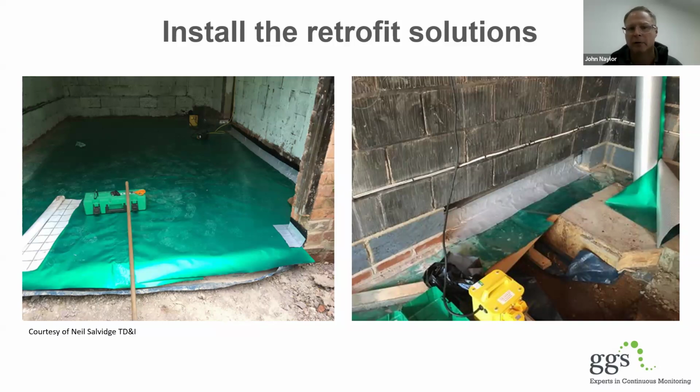So rather than knocking the whole wall down, we can break out sections of the wall and seal through it. We then reinstate those bricks and move on to the next section. You can do this in several stages around the building, and we can get that membrane fully installed throughout. This is courtesy of Neil Salvage. I'm sure plenty of you know Neil. And it's something that has been done successfully. But again, time, effort, cost, planning. It's not a quick fix.